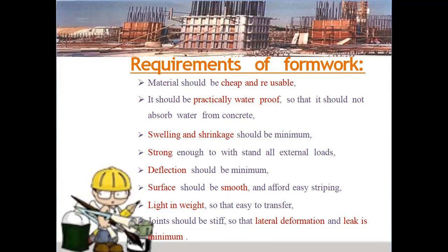So a waterproof material should be used for the formwork so that it does not absorb any water present in the concrete. The swelling and shrinkage should be minimum. It should be strong enough to withstand all external loads applied on the formworks.